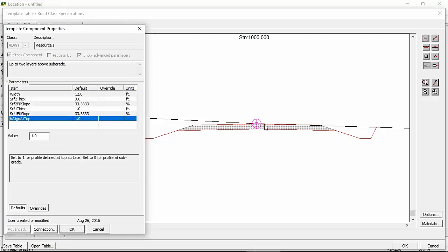Yeah, and the alignment in our old default roadway component, this is meant to replace that. The alignment was either at the running surface or at the subgrade. So as you can see, I've changed the left one, but not the right one. But now the alignment is below the surfacing on the top of the subgrade. So that's an option in this template.